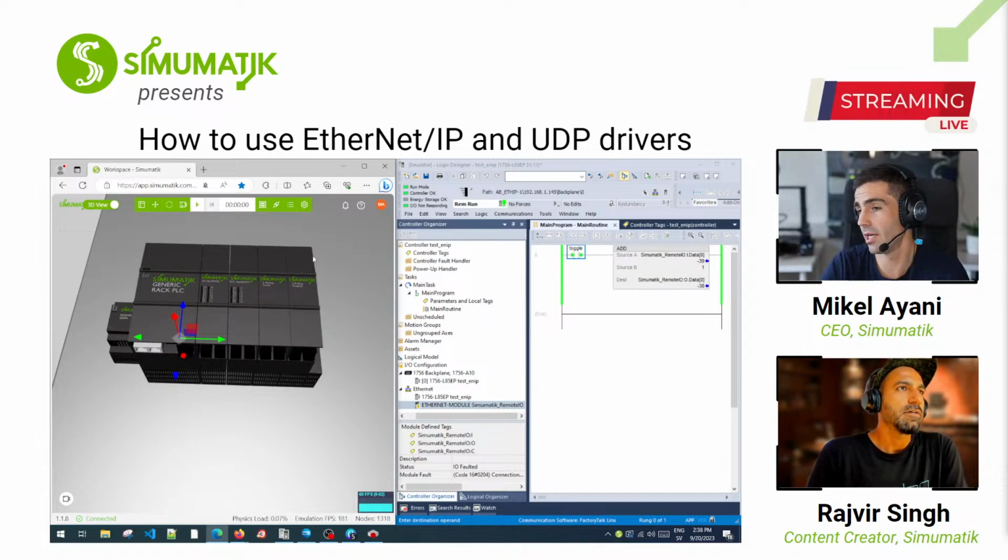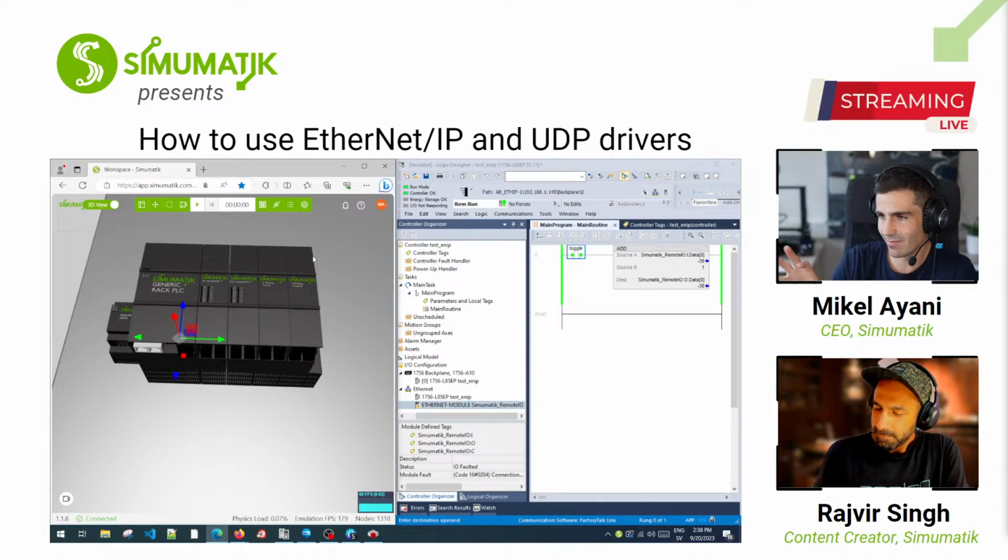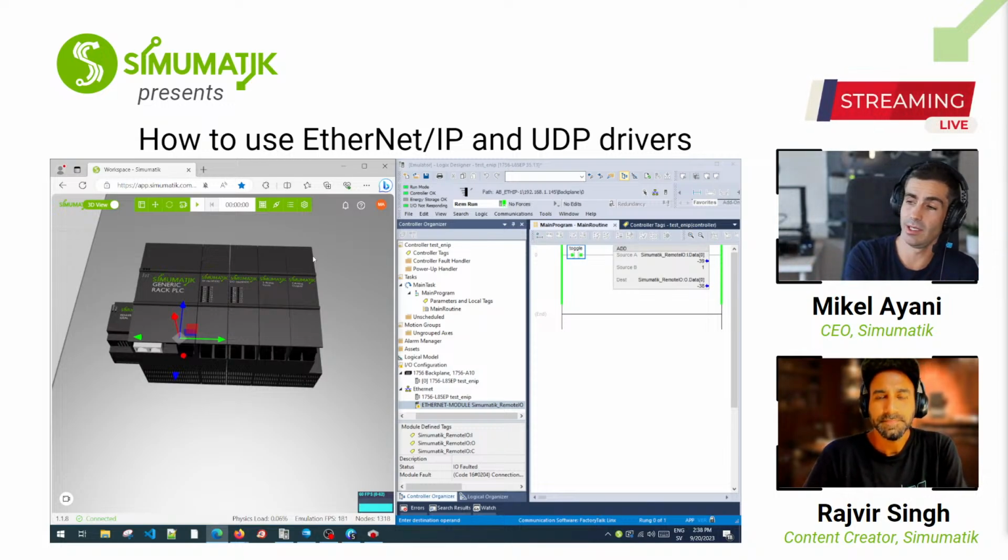Yeah. So we explained briefly how Ethernet IP differs from other drivers we have in the gateway. The difference is that this is not as proactive as other drivers, but more reactive, and it requires some setup in the computer to add the extra IP addresses we may need to reproduce or emulate these remote IO modules.